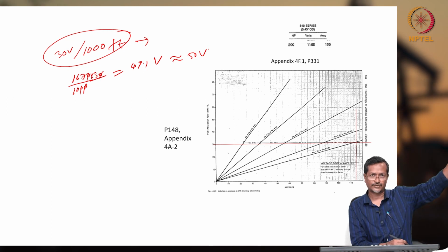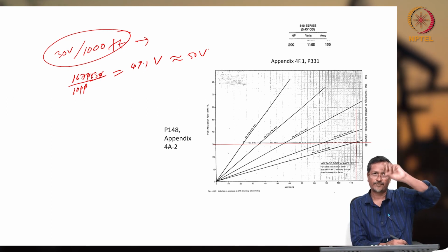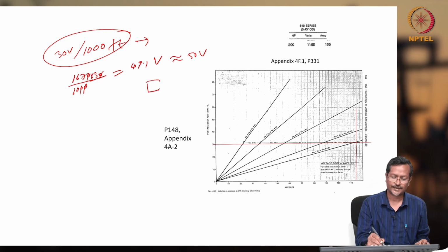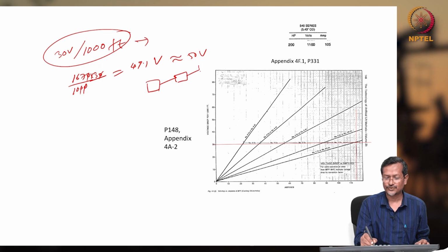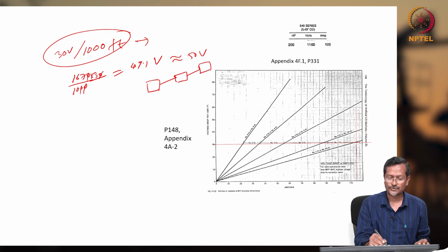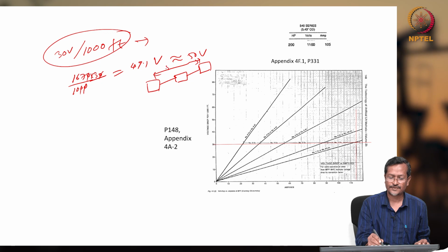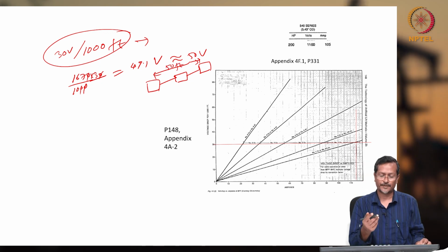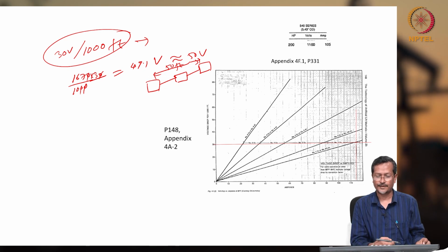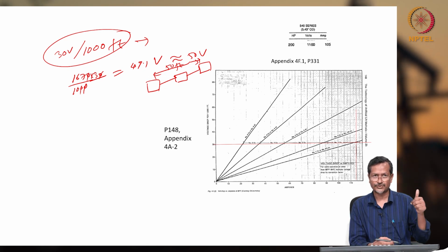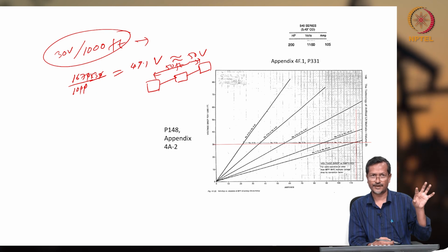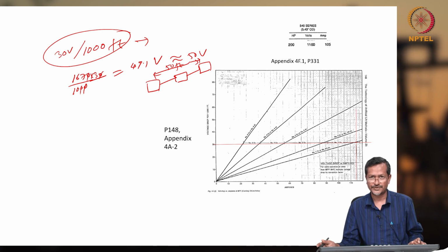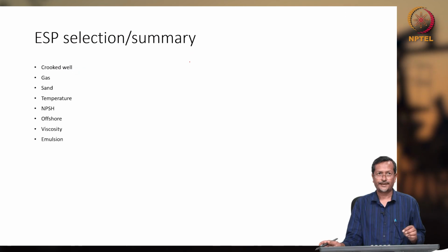If we calculate the surface cable also, for example it is about 50 feet, you can remember the wellhead is there, then the junction box, then the switch, right? So this total distance is about 50 feet. If I add the 50 feet, then my voltage drop will be a little bit higher, because your switch box will have all the voltage and current measuring and controlling equipment. So from there you have to see how much voltage drop there is through your wellbore.